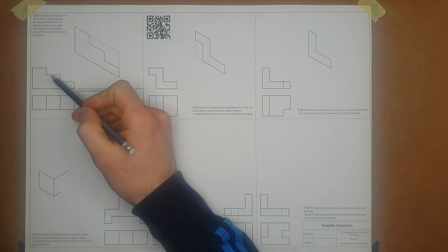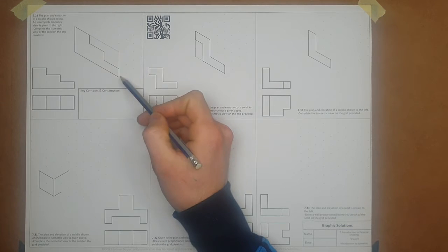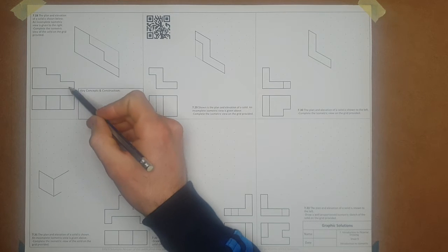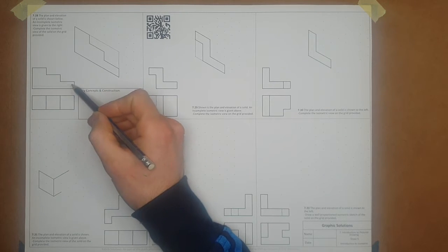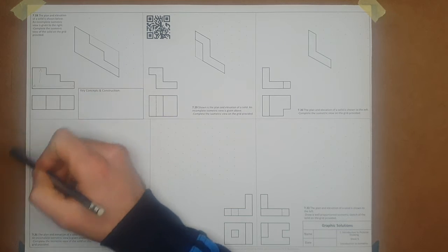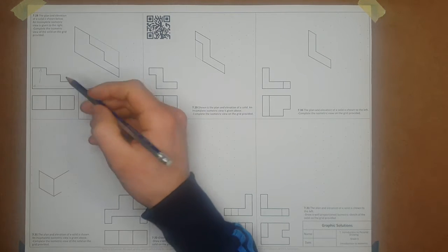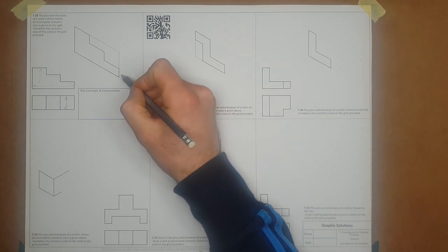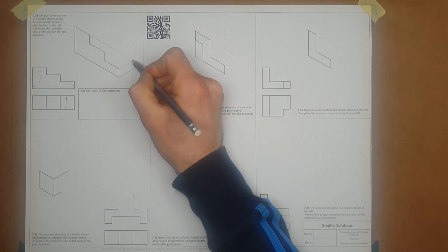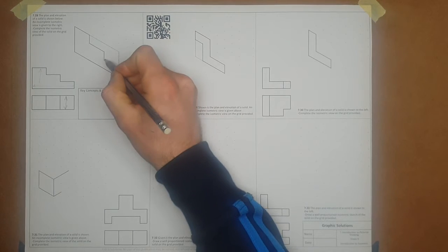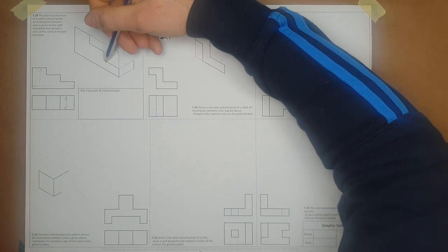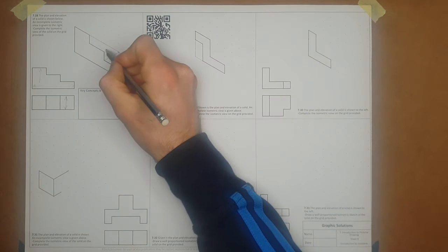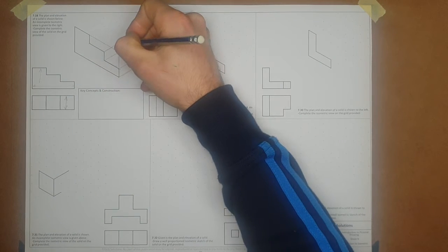The elevation is, as I said, flat, so that's drawn full, all boxed out along the grid. That gives me the lengths of the object and the height of the object. All the lengths and heights are used, and there's only one dimension remaining, and that's the depth of the object. The depth is 2 boxes. So I'm going to go back by 2, and draw it in. Whatever angles I was using at the front, I can use at the back. This whole page is freehand only. Back by 2.